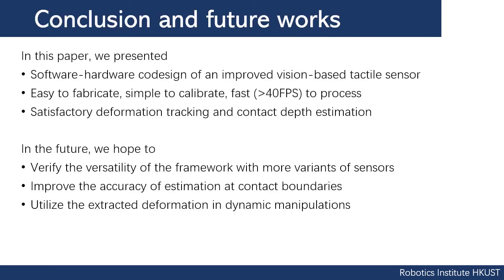In this paper, we presented a software-hardware co-design of an improved vision-based tactile sensor. It is easy to fabricate, simple to calibrate, with very fast processing time, over 40 frames per second. It achieves satisfactory deformation tracking performance and contact depth estimation.